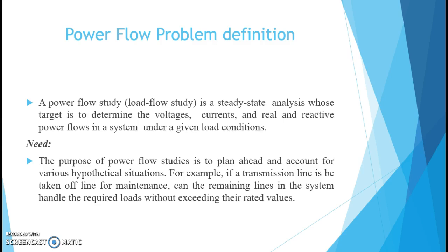The main objective of the power flow problem is to find the bus voltages, bus angles, and the real and reactive power flow in the system, that is, in the transmission lines. This is our main goal. It can be calculated with the help of different algorithms like Gauss-Seidel, fast decoupled, and Newton-Raphson methods. The algorithms, modeling, and problem solving methods we will see in the next class.